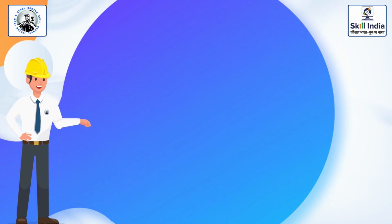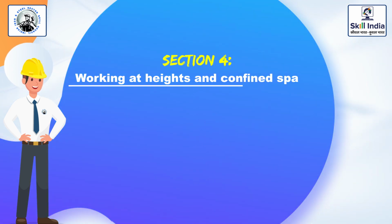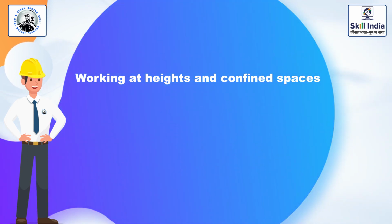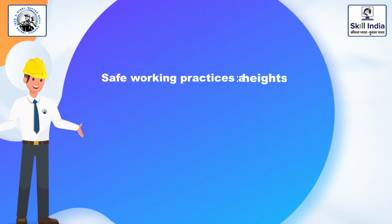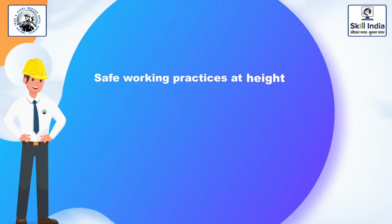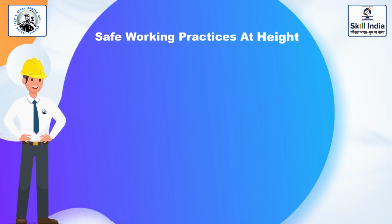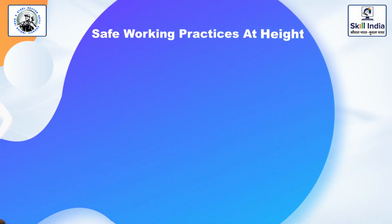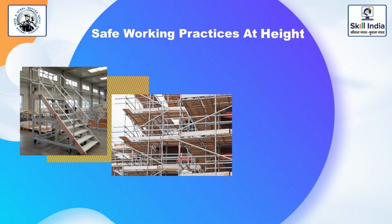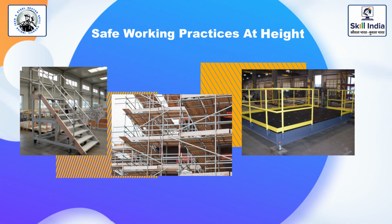Learners, welcome to the next section. In this part, you will learn about risks of working at heights and confined spaces, and what are the safety precautions you need to take while working at heights and confined spaces. While working in a plant, you may have to perform activities at height for which you will be using ladders, scaffolds, and platforms. Here you need to follow strict safety protocols to carry out the work safely.